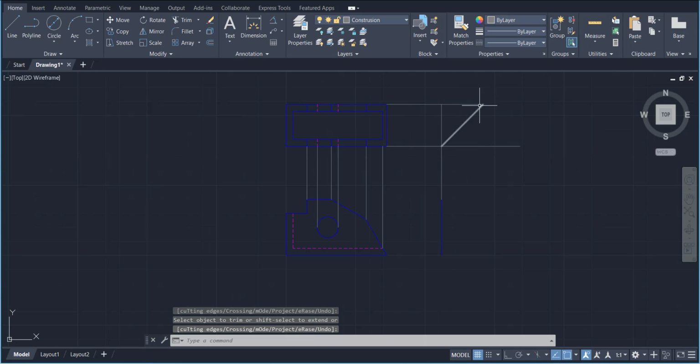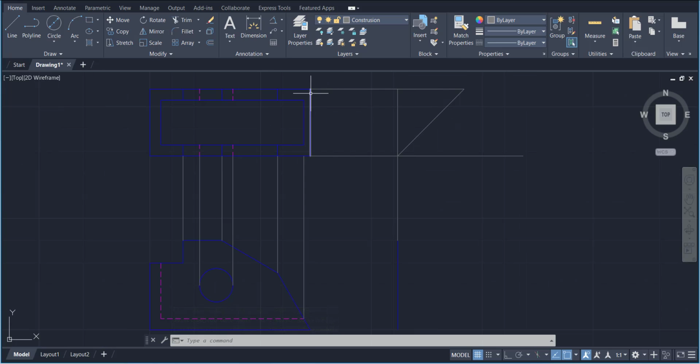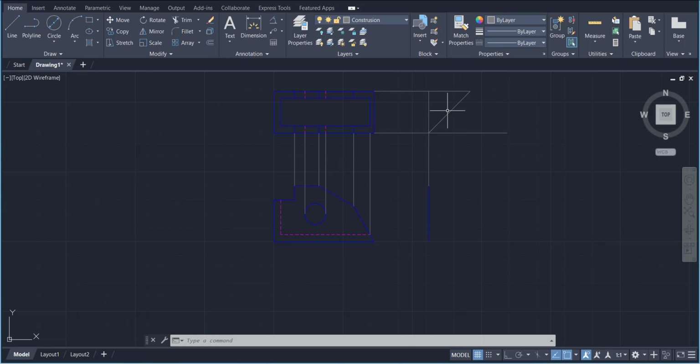Okay, now to transfer the point from the top view to the side view, on every line from this top view which will meet on this middle line, we are going to draw a horizontal line from that. So this one I'm going to draw a line like that, and till this point, drag this point like that.